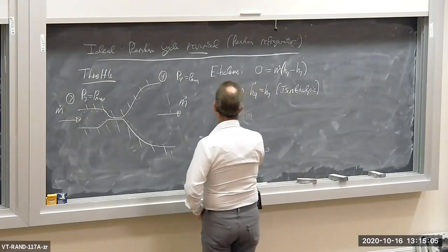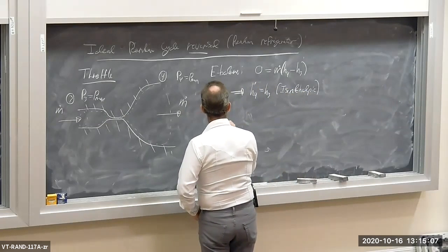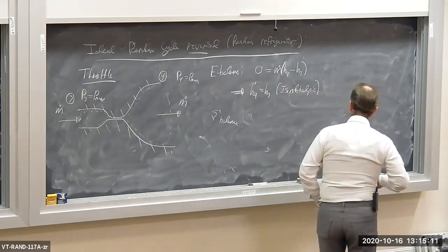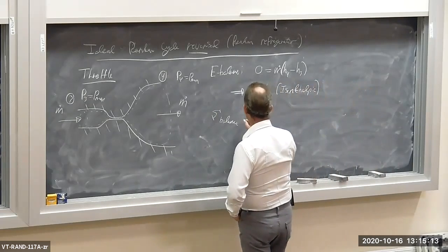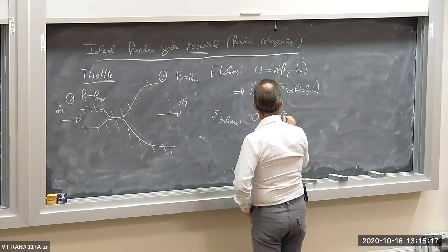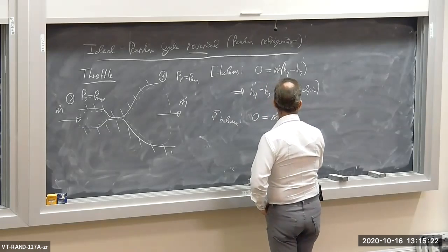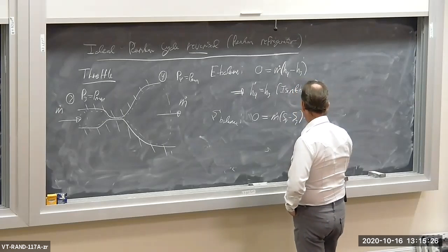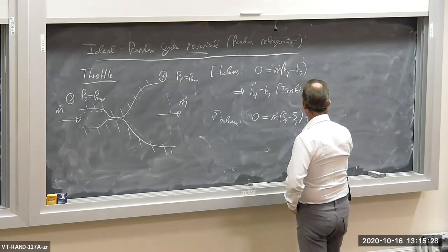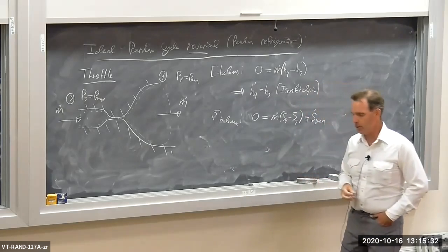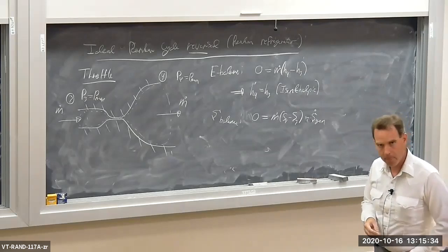So the entropy balance, there's no heat transfer, so the entropy balance says 0 equals m dot times S4 minus S3, minus S dot gen.